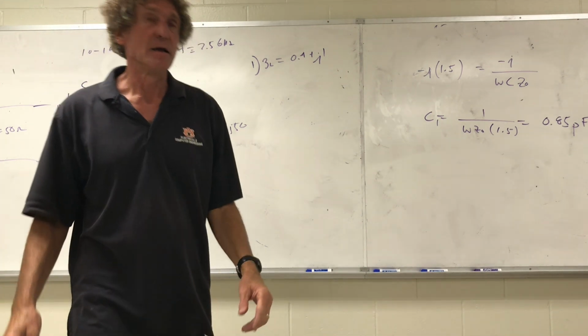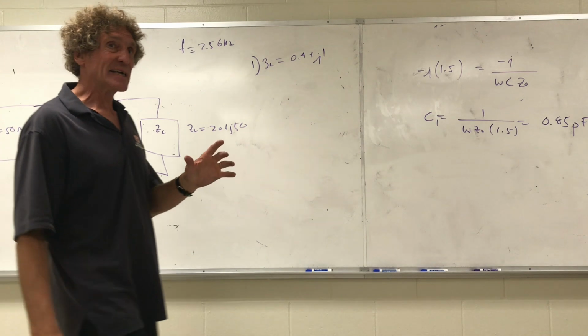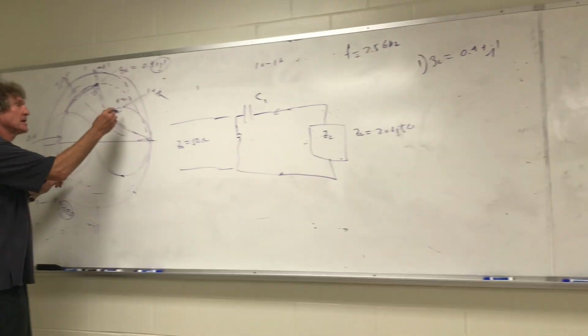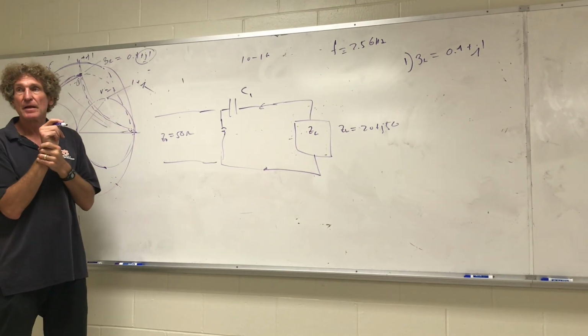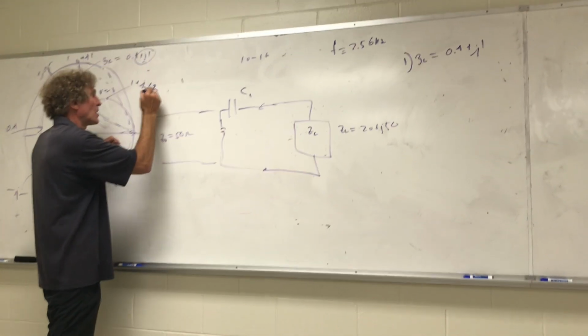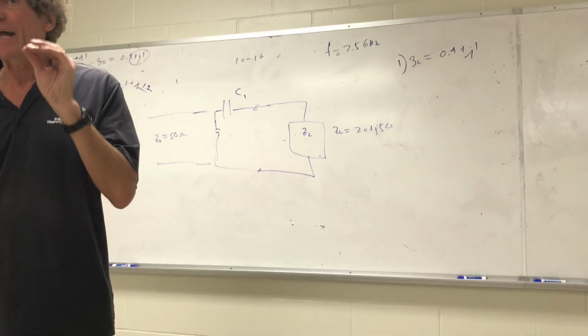Where did that 1.5 come from? Look, if I start here, I'm at J1. I have to get down to minus 0.5, that's a difference of 1.5, it's negative. Now, next, I'm here. This value is 0.4 minus J0.5. 1 over that will land me here, but I need the J value. 1.2. Confirm it, anyone? Yeah, 1.2. We're in the admittance domain.